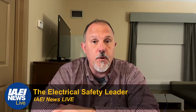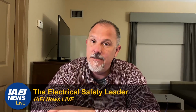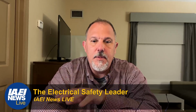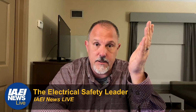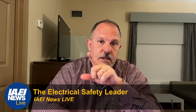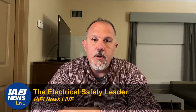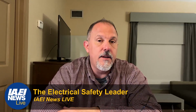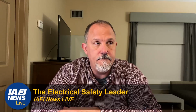If the receptacle is further than 6 foot, but the appliance is right next to the sink or within 6 foot of the sink, you're going to GFCI protect that receptacle, even though the receptacle is outside of the 6 feet, because the fixed or stationary appliance, and we can have the debate on what is a fixed or stationary appliance, that's fair game. That fixed or stationary appliance, if it is within 6 foot of a sink, regardless of where the receptacle is, it would have to be GFCI protected. Where is that going to hit?